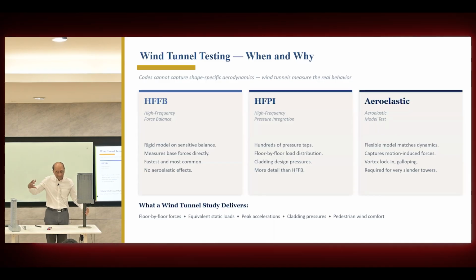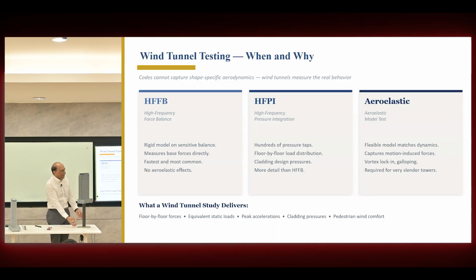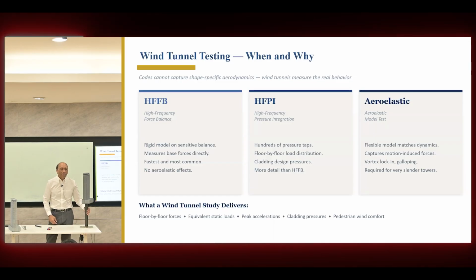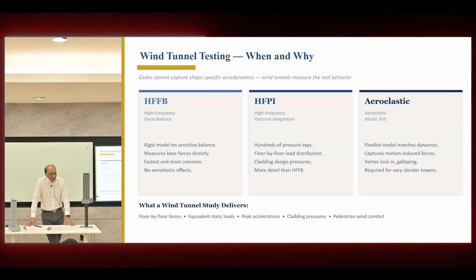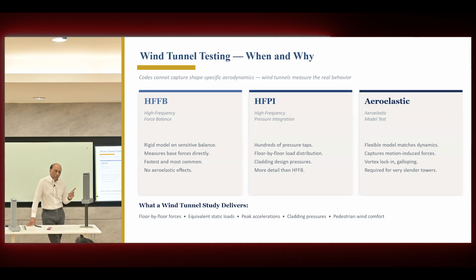So normally this will be rotated. In the wind tunnel, wind will be blowing like this. So at every angle, every 10-degree rotation, moment and forces at the base will be recorded by the load balance at the base. So we will get a complete force and moment profile for every angle of rotation. And this will be used for overall structural load calculations.